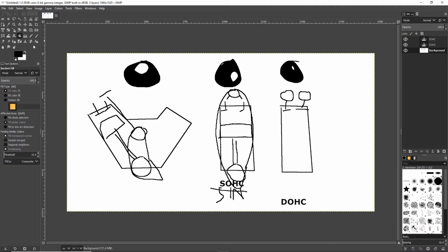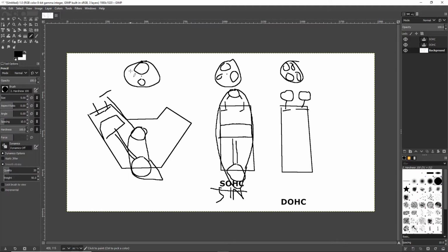But if we look at the difference between the dead space in here that we're not using, there's much less here, so way more air and fuel. And this is what we use on just about every engine in the parking lot. Everybody's moved to this double overhead cam for this reason. So just like the other two, crankshaft down here, but this one has 2 camshafts and a chain or a belt holding it.